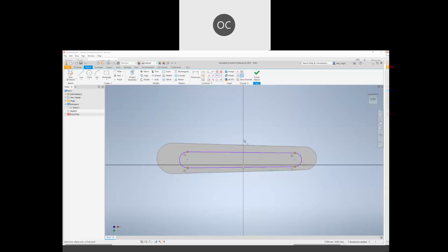The next task will be to align this secondary sketch to the middle of this primary feature. So what we can do, first, is to put it horizontally to the center point of this initial arc here. So the thing that you ought to do now is to apply project geometry, please.